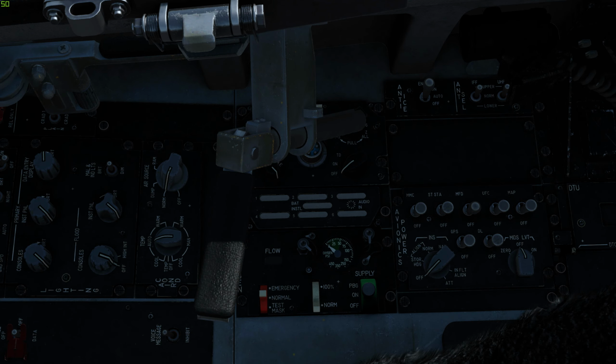In the ram position, engine bleed valves are closed and the cockpit vents to external air pressure. Ram air valves are opened and ventilate the cockpit and avionics. External fuel tank pressurization, cooling, and the other ECS functions are disabled.